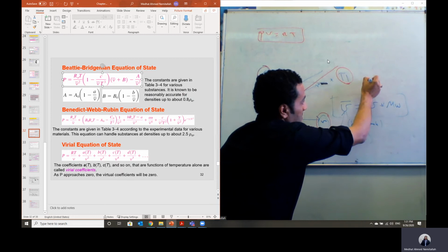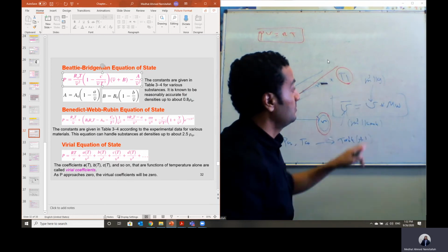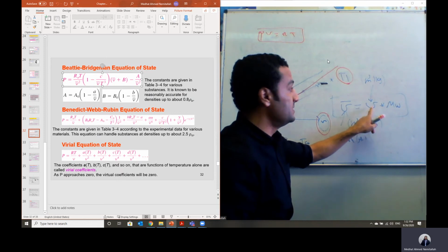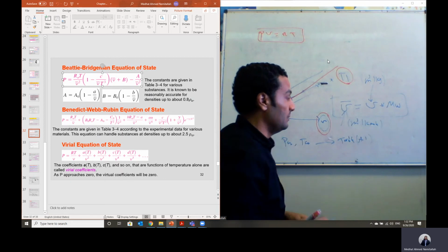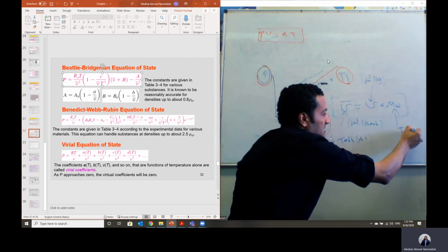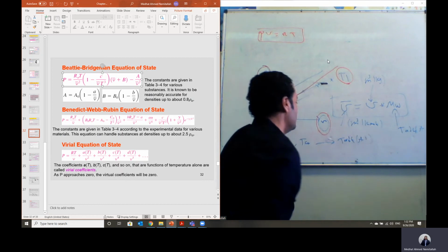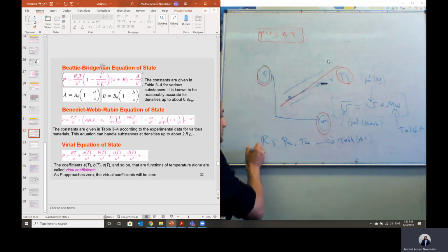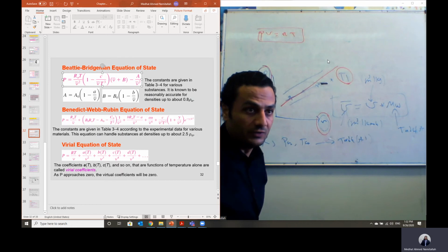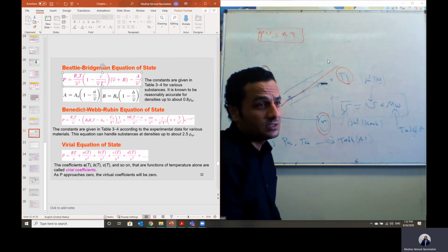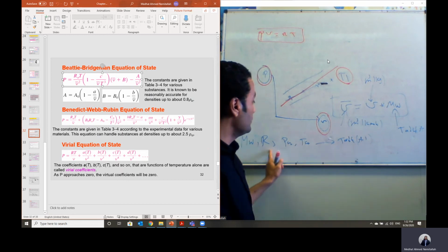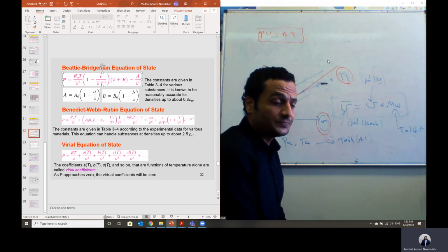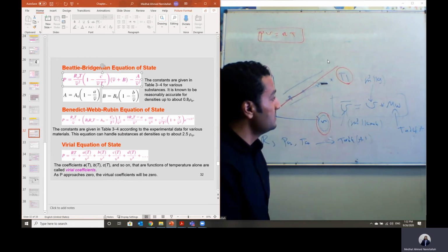The specific volume v, as you know, is calculated in meter cube per kilogram. To convert, given a specific volume, I will multiply this value by the molecular weight, then I can calculate the molar specific volume. And the molecular weight, as we said, can be obtained from table A1, where it is given for any working fluid. So depending on the working fluid, let's say air, we can go to table A1 and get the gas constant, molecular weight, critical pressure, and critical temperature, if needed. Then we can just substitute here.